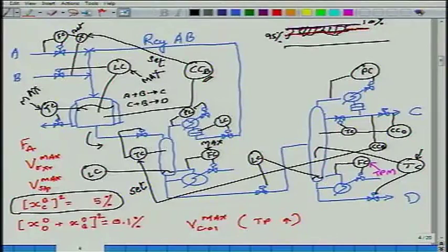Temperature you could have jacked up. What else could you have jacked up or down? Level is already at max. Heat flow rate. Well, feed flow rate is already under ratio control and level control. That's not in your hands. The fresh feeds are already under level control and ratio control, right? The way it is drawn there. Yes or no? You cannot move that.